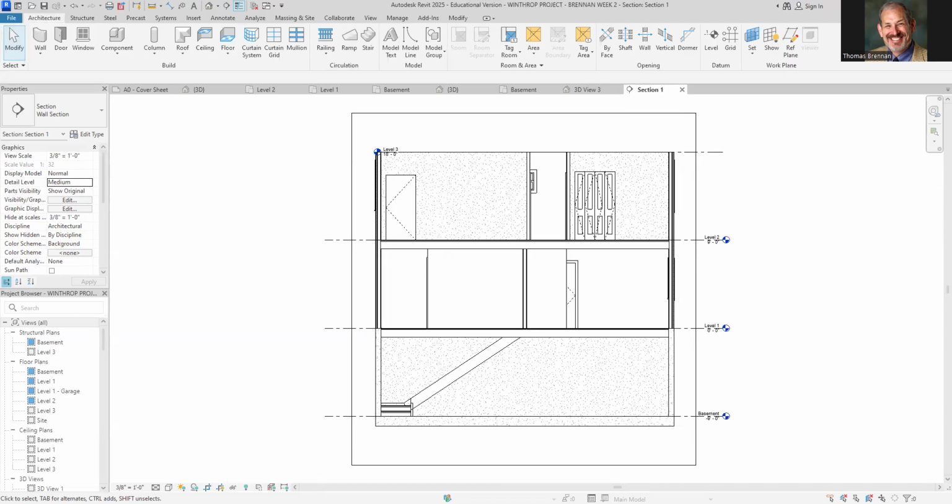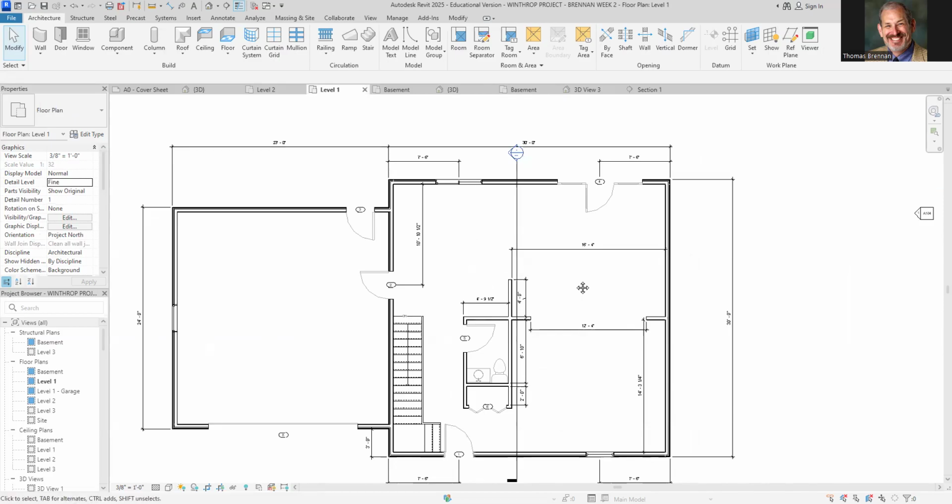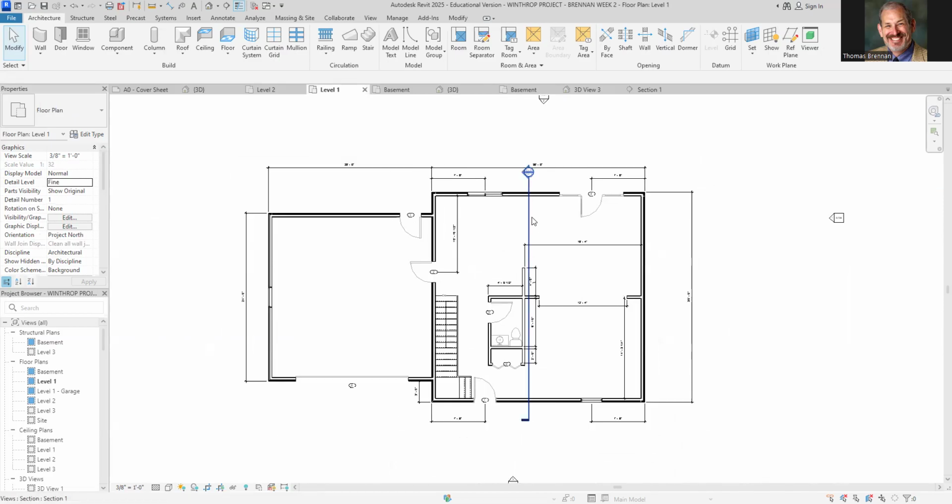Yep. Okay. So what you want to do is you want to go ahead and put in the section, just like I did. And so what you're going to do is you're going to go to your level 1. And when you go to level 1, you're going to make a section. It's going to go all the way across. And you won't be able to see it. It'll give you a little message down here. When it gives you a little message, you click on the light bulb. And it's going to say reveal hidden elements, and then you'll see it in a magenta color. You'll click on it, right click and say unhide in view, and then you'll flip it. And then at that point, when you double click on it, you'll be able to see the section. So that's all we're doing right now.